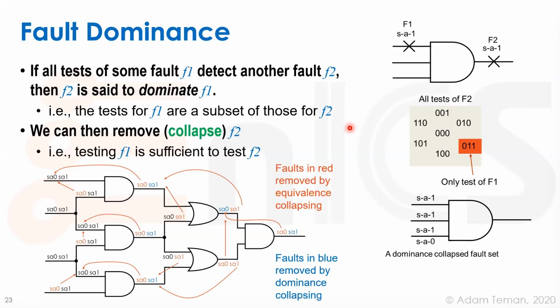Okay, so we just went over very briefly that the fault model gives us some sort of properties between different faults that go along a gate that show equivalence and dominance, and then we can get rid of them, and we can make the number of faults that we actually have to check much fewer than the actual number of faults because they have this type of equivalence. So that helps us reduce the complexity of the problem. Still, it's a hugely complex problem.